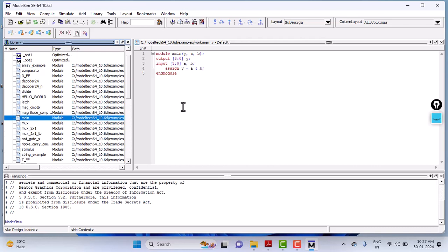And B also I'm giving like this, 4-bit. This is 3, 2, 1, 0. That's why I'm mentioning 3 to 0. Are you getting it? 3 is the MSB and 0 is the LSB. Look here, 3 to 0. Whatever 4-bit number you give like this, the bit position 3 becomes the MSB and bit position 0 becomes the LSB. Understand? What if I declare something like this?